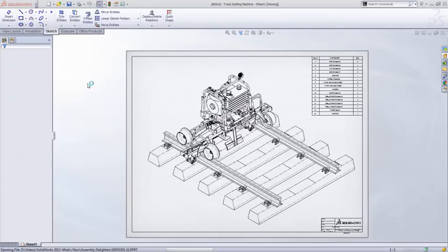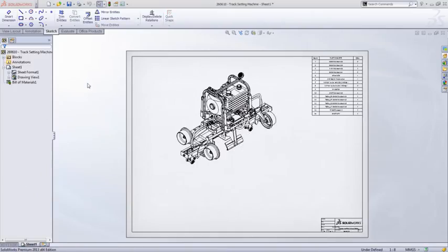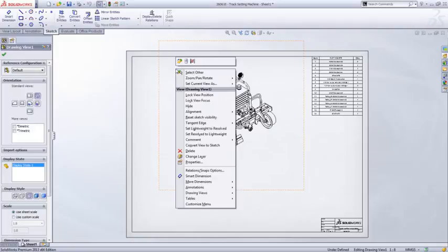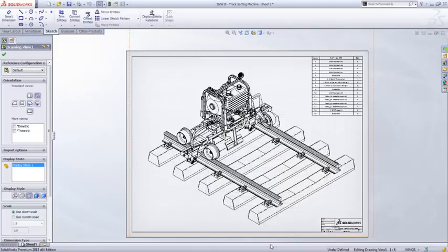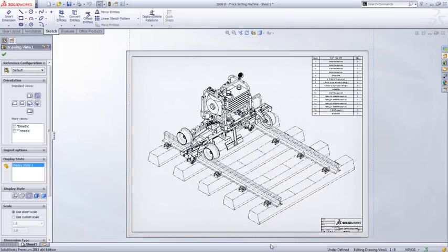As mentioned, envelopes don't contribute to top-level design elements. For example, if we open a drawing containing this, it's immediately removed from the bill of material and the view. If we would like to show this reference geometry, we can choose any view and opt to enable the Show Envelope option. Any envelope components will be immediately displayed with the unique phantom line type.